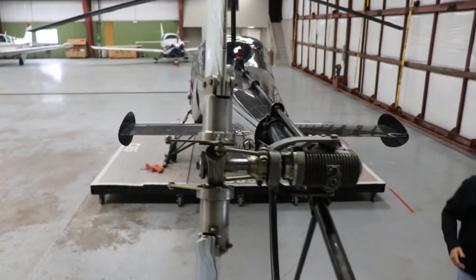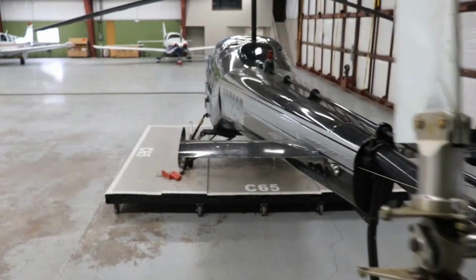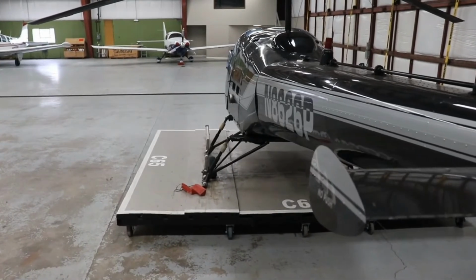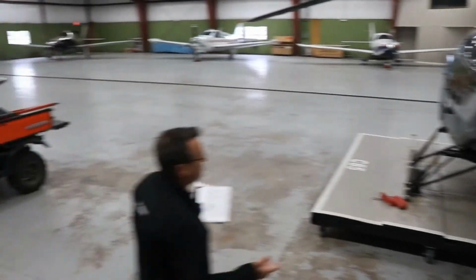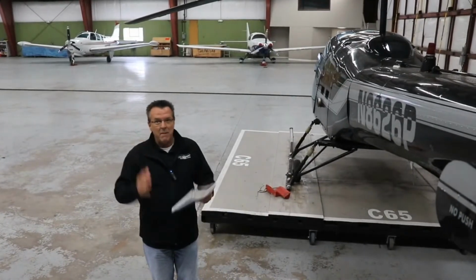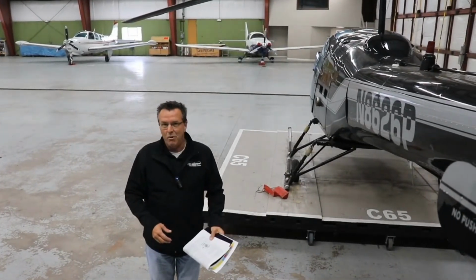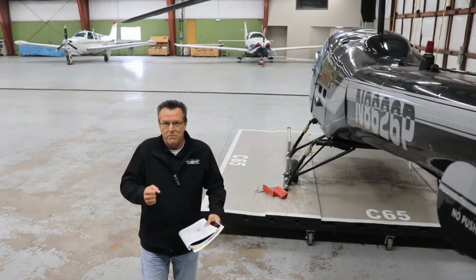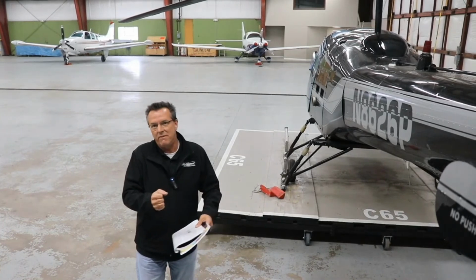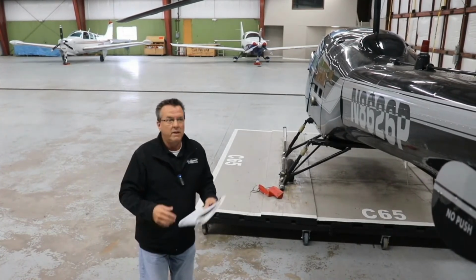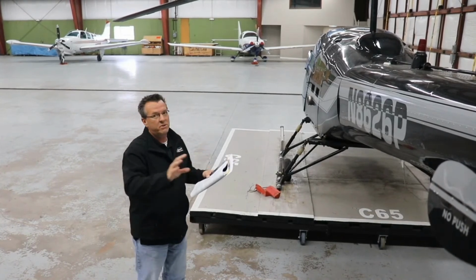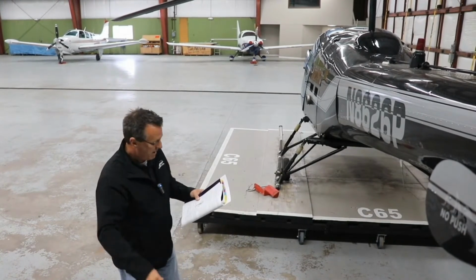In other aircraft, it may be done through cyclic rigging. Some aircraft don't even counteract it at all. I flew a BK-117 for a couple years, and they told us in training that it's not built into that system. So that skid's always hanging low on the left, your right skid always comes up first, and you're always holding to the left to counteract that effect of torque. So depending on the aircraft you're flying, you need to know how they compensate for that in that aircraft.